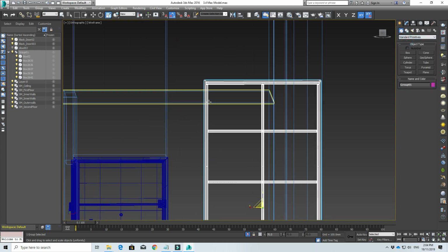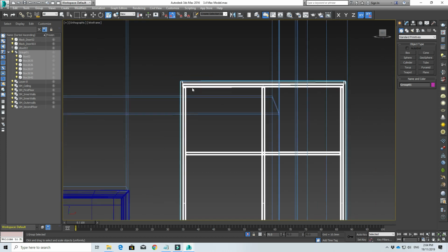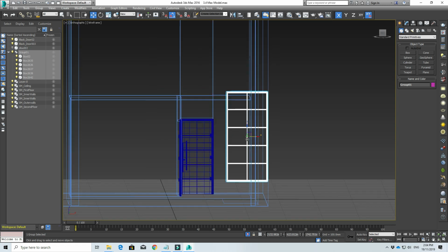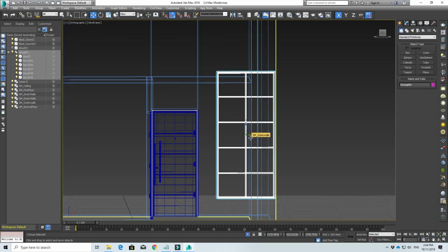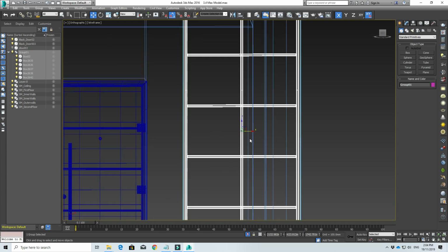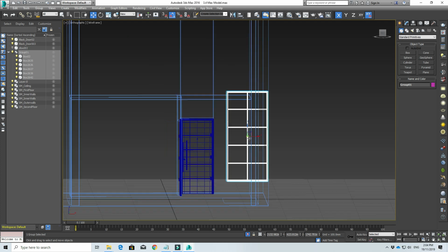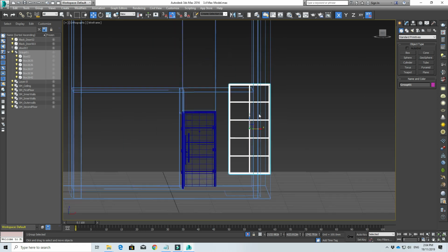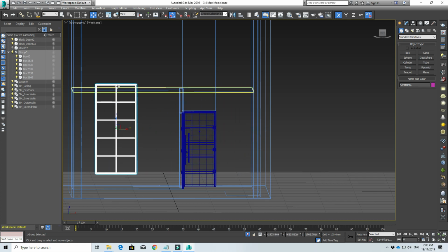But for Unreal Engine, especially if you are using static lighting, these primitive shapes actually work the best, because of light maps. There are a lot of ways to model the window using other modifiers, but primitive shapes like this are the best. Which is also why I've chosen this window. So in case you are modeling your own windows, just take note of that. Of course, you can always model your own window and experiment with the light maps, but the best results always come from using these primitive shapes. Okay, so once I have scaled this window, let's move on.